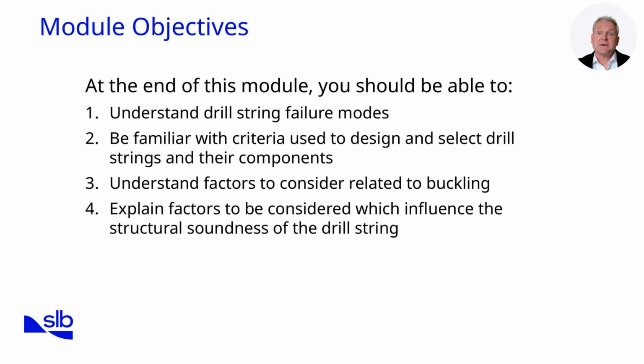Fatigue develops from repeated stress cycles, and a well-designed string must minimize these risks by using proper material selection and monitoring stress concentrations. Next, we focus on bending stresses, which arise when the drill string negotiates curvature, particularly in directional wells. Understanding bending stresses is essential for preventing localized overstressing and failure.